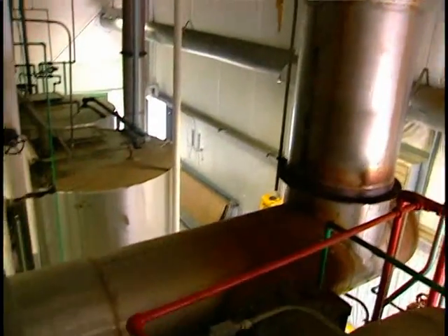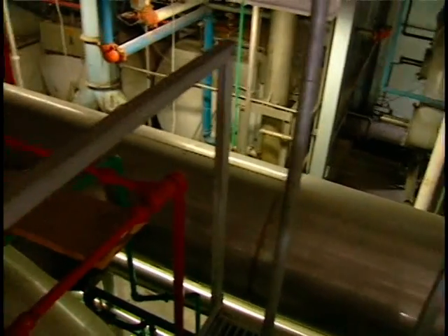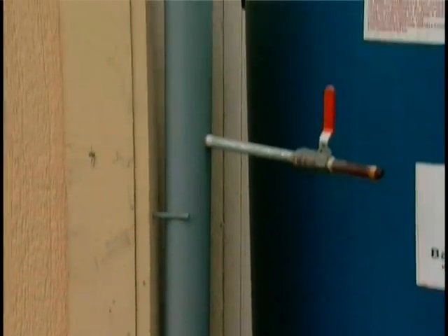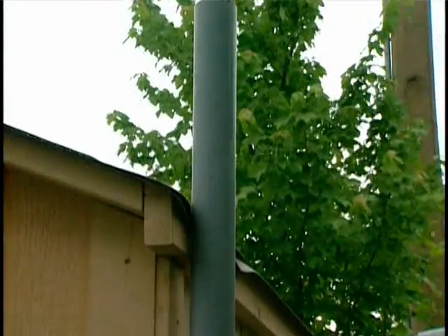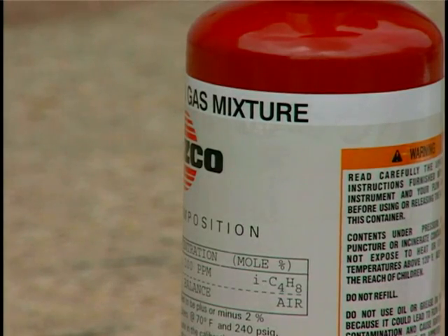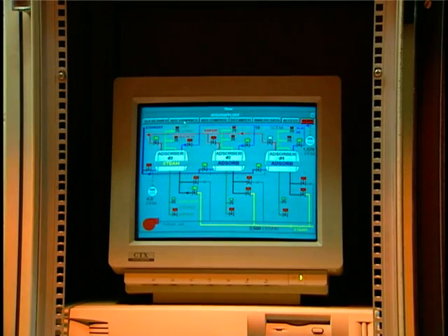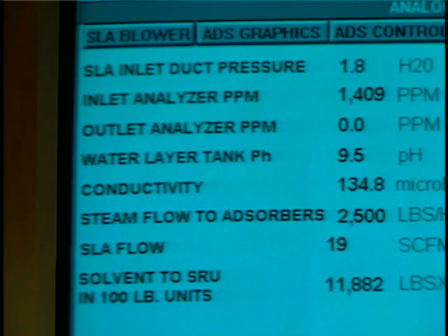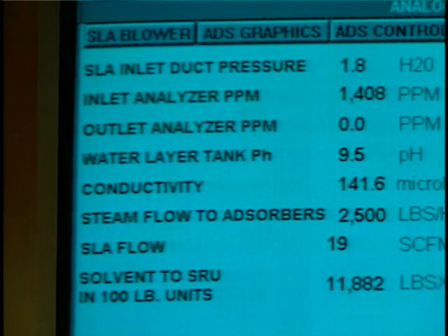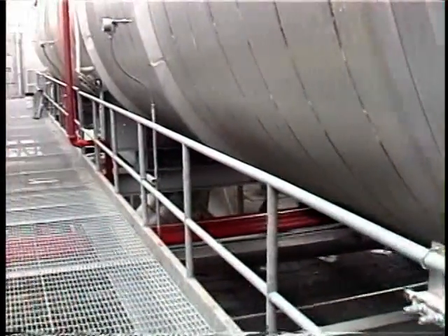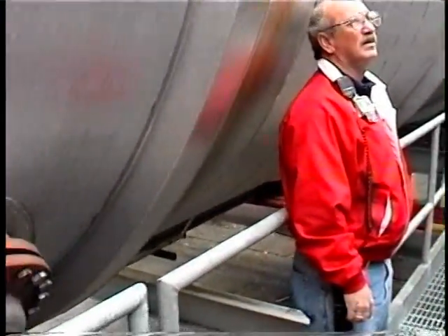Both permanently mounted and portable analyzers can provide an accurate indication of the outlet concentration when they are calibrated for the specific compound or compounds present in the gas stream. Often, outlet concentration measurements required by regulation are based on calibrations with a reference gas. The instruments are calibrated using a readily available organic compound such as methane, propane, hexane, or 1,3-butadiene as specified by the applicable regulation. Under these conditions, the instruments will provide a measure of performance relative to a compliance limit expressed in units of the calibration compound or as carbon.